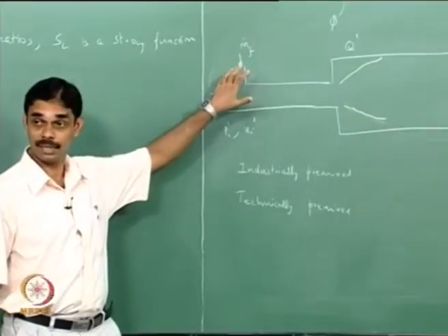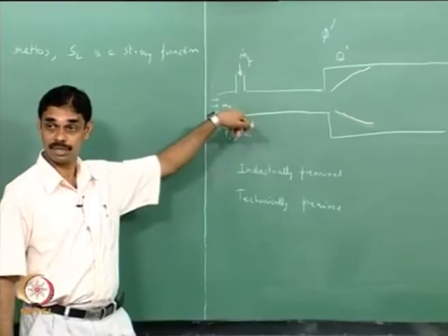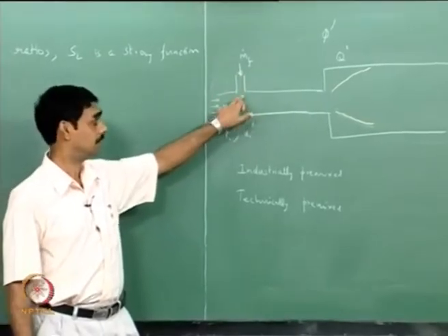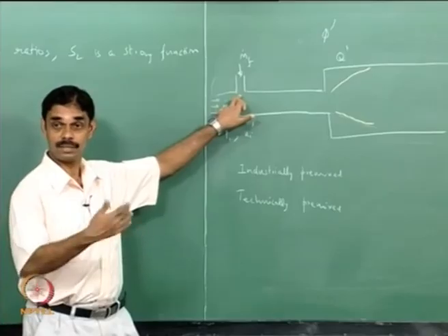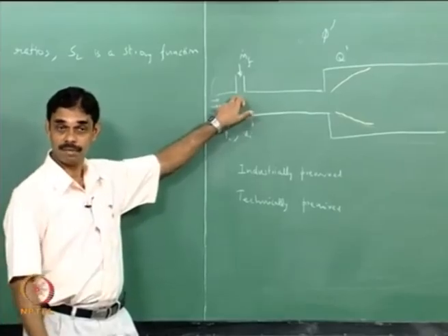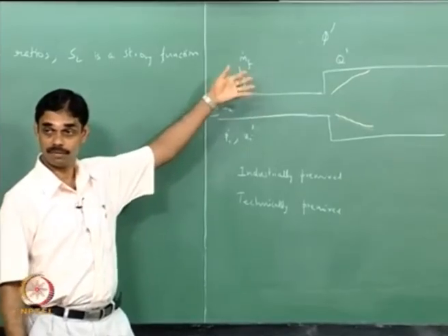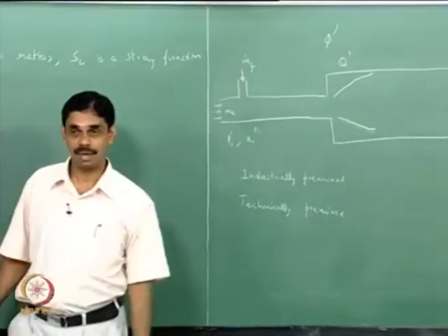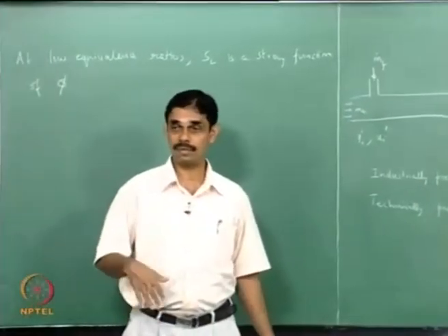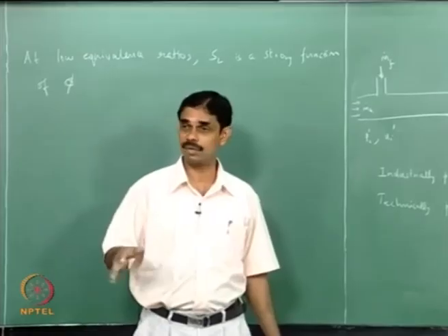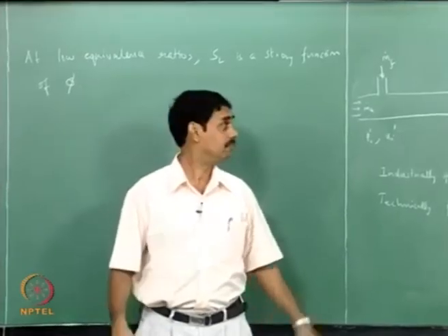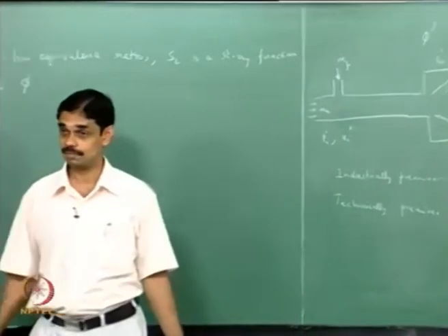When the pressure goes to a minimum, it's going to allow more fuel to come. So when pressure here is low, you have a higher delta P, and so there is more flow rate coming. When the acoustic wave has a maximum, you have less pressure drop, so the flow rate will be less. If you are thinking quasi-steady, then the fuel flow rate will oscillate like square root of delta P approximately. When would this mechanism not work?